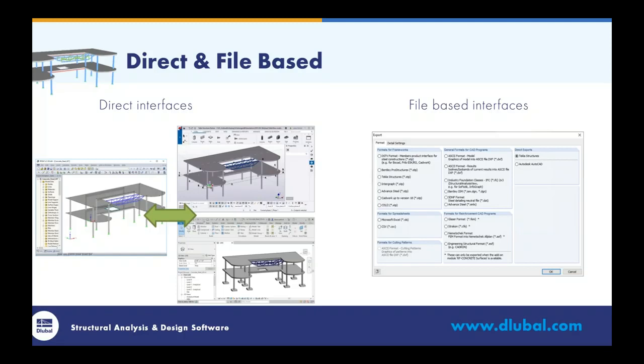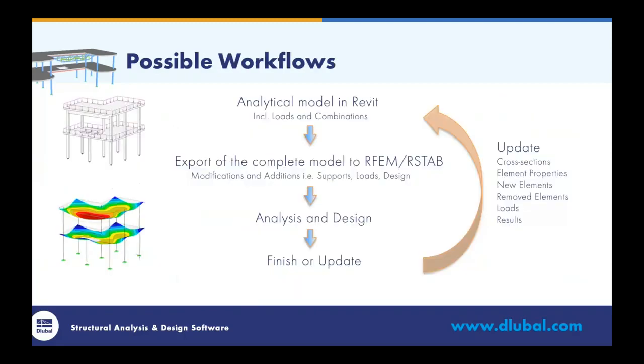Before I show a live demonstration of the interfaces, I want to give you an overview about the possible workflows. The first workflow is maybe the most common one. You would start in Revit. So maybe the architect or the BIM manager created the model in Revit. And while he was defining the columns, the beams, the slabs, and so on, Revit allows you to automatically create the analytical model in the background.